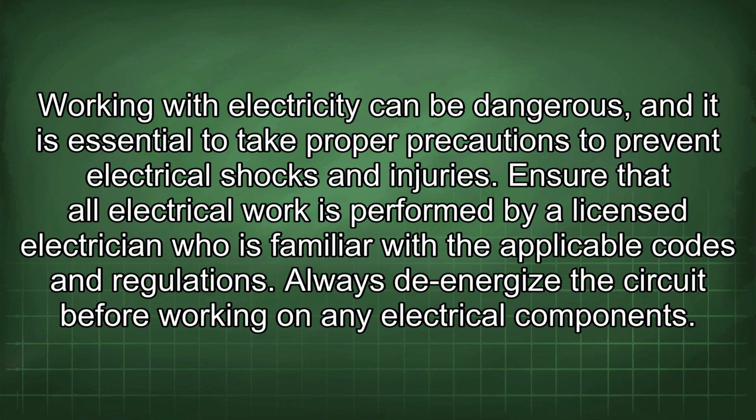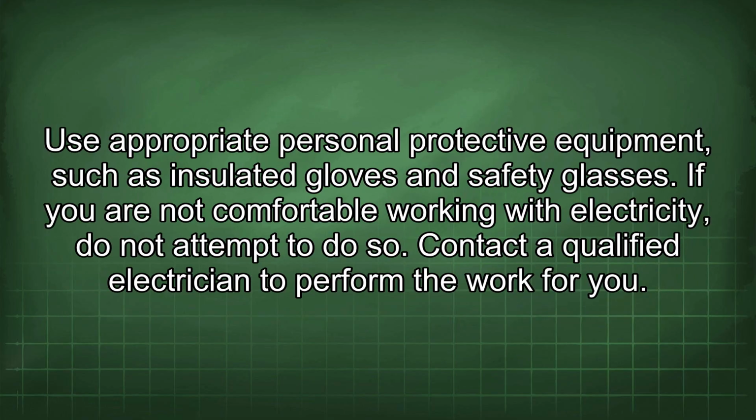Always de-energize the circuit before working on any electrical components. Use appropriate personal protective equipment, such as insulated gloves and safety glasses. If you are not comfortable working with electricity, do not attempt to do so. Contact a qualified electrician to perform the work for you.